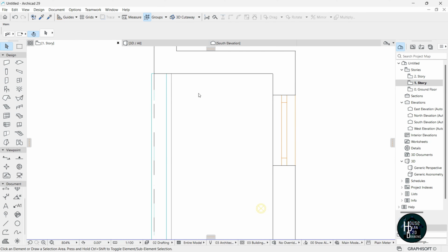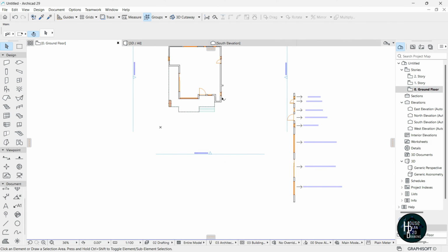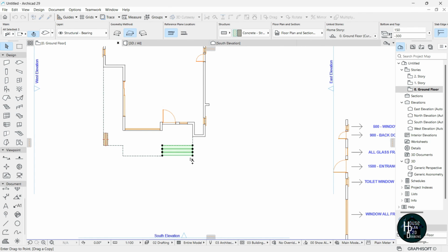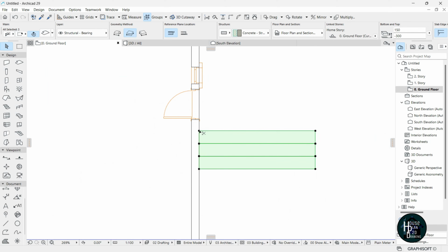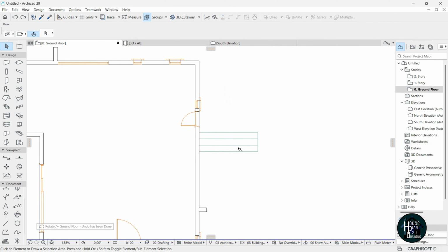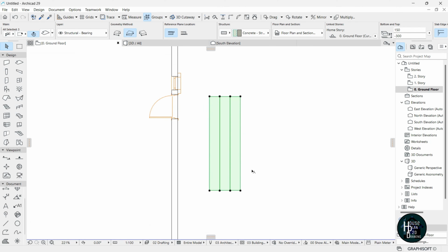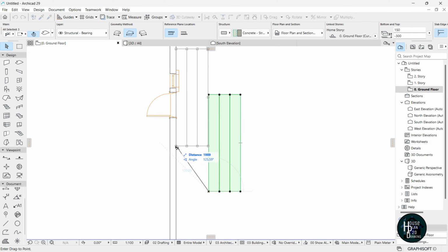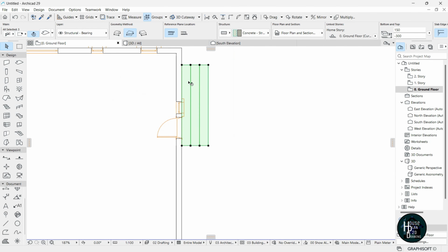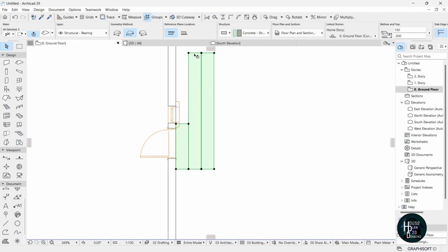Also go to the first story and let's add that there too. We're going to go to this ground floor plan, just highlight all of this, press Ctrl Shift D on your keyboard, select this, and let's try to just put this here. Press Ctrl E to rotate it. Okay, but in the latest Archicad feature, you can just align this and press Ctrl arrow, and it's going to rotate for you automatically. Then press Ctrl D, and let's put this here. Let me try and adjust that properly. Okay, and let's try and just reduce it to somewhere around here like so.